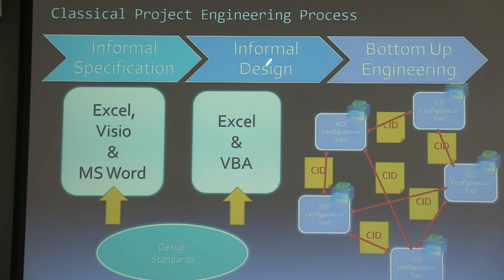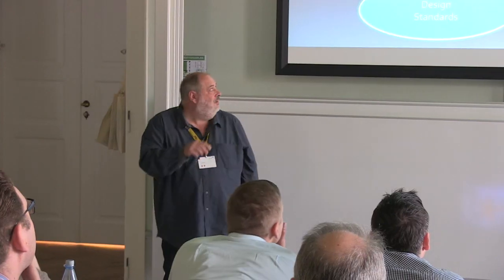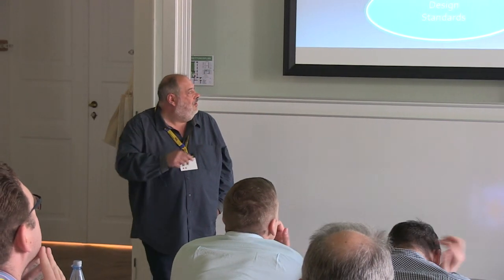But more or less, this is also an informal design where the standard is really excellent work. And then the system engineer knows what he has to do. Then he goes to the shelf, takes the IEDs from the shelf, and with the IED tools of the different vendors, he is just configuring the IEDs. So he looks, what signals do I have for this feeder, what GUIs do I need to implement, and then he does this on the IED level.